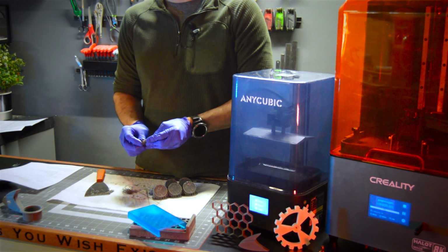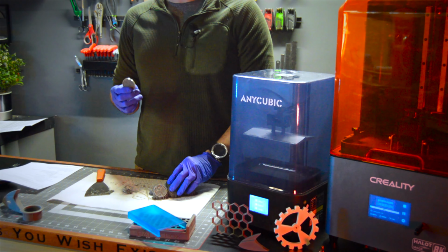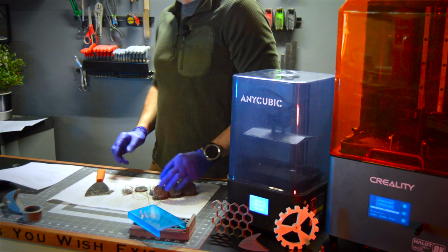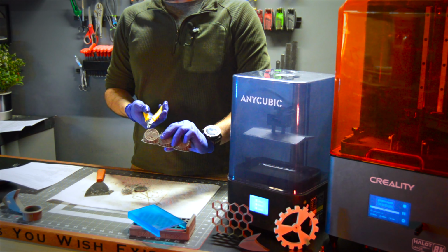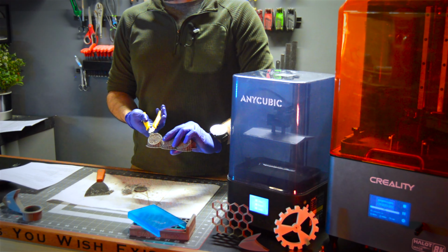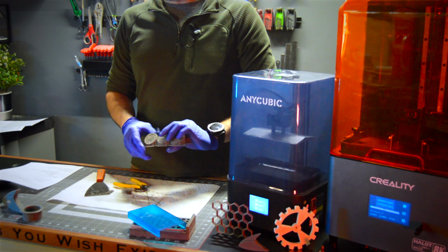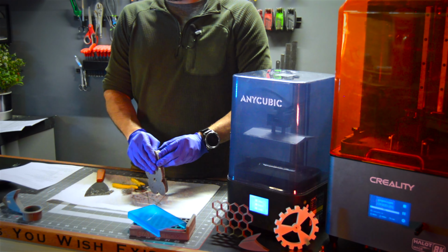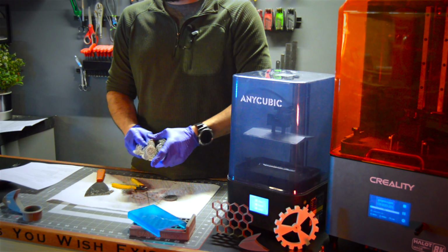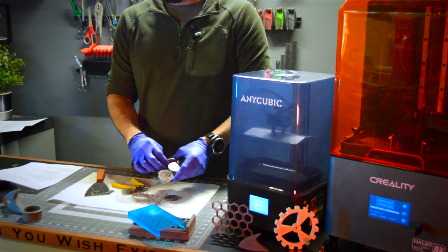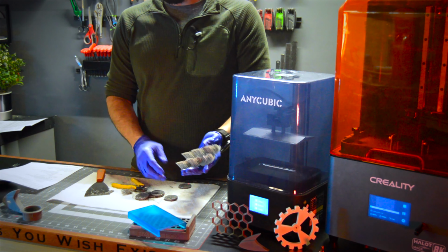However, for larger objects, like I recommended placing larger supports, this is not as simple a process as breaking them off, and you may need a set of pliers designed for small objects. With that, you can simply clip the supports as you go around the object to remove it from its supports. So we'll go ahead and skip through this quickly as I remove these supports from these prints. Again, it's a simple process the majority of the time.